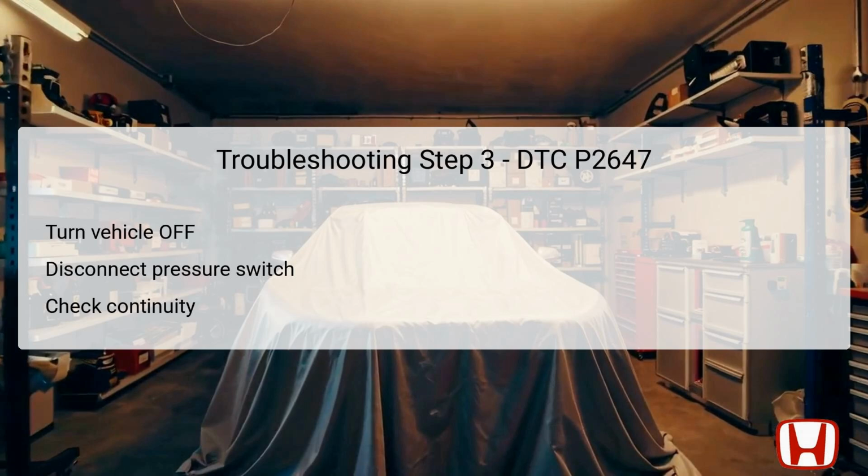It's crucial to ensure the vehicle is off during this test to avoid electric shorts. If continuity exists, the circuit is likely functioning properly and calls for further diagnosis. Conversely, if continuity is absent, it strongly indicates an internal fault in the rocker arm oil pressure switch A, warranting replacement of the component.